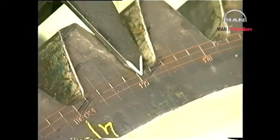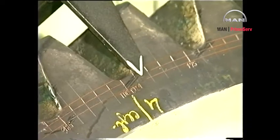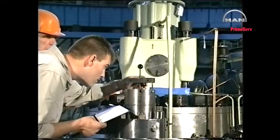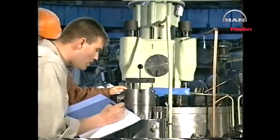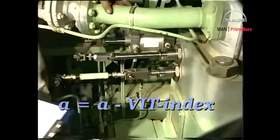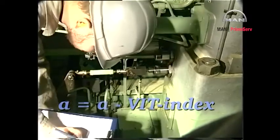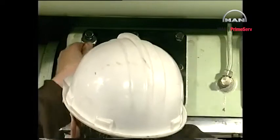Turn the cylinder concerned to top dead center. Read the actual fuel pump lead directly on the measuring tool. Read the VIT index. If the VIT index is not at 0, the lead must be corrected before it is recorded in the engine logbook. Carry out fine adjustments through the small cover.